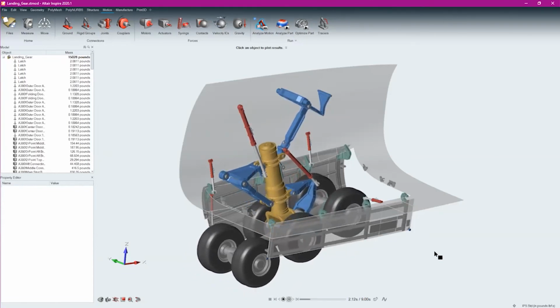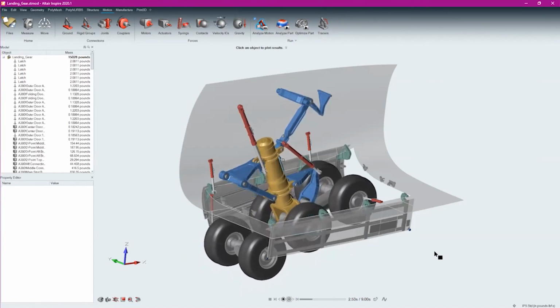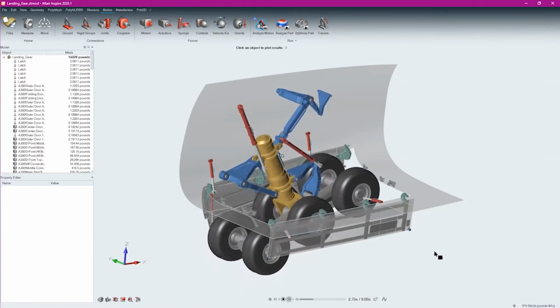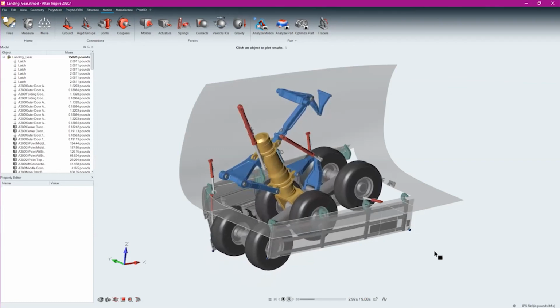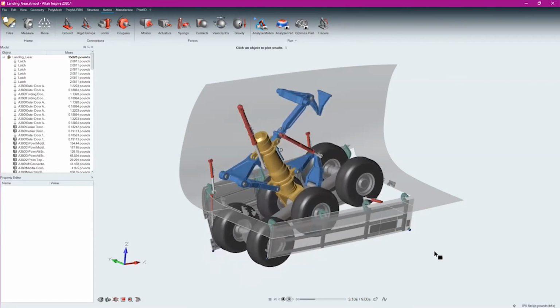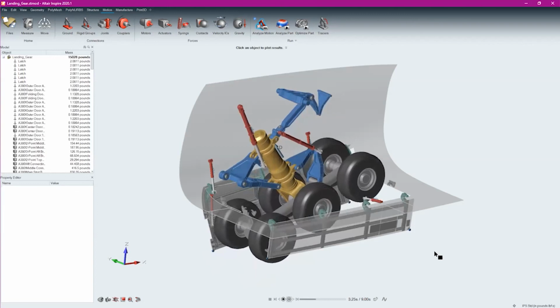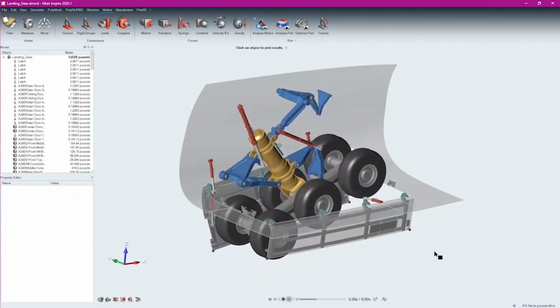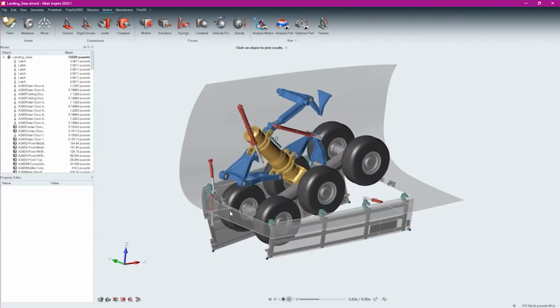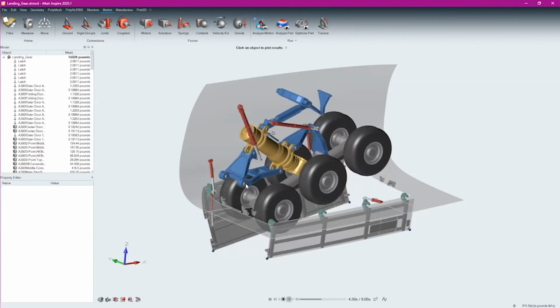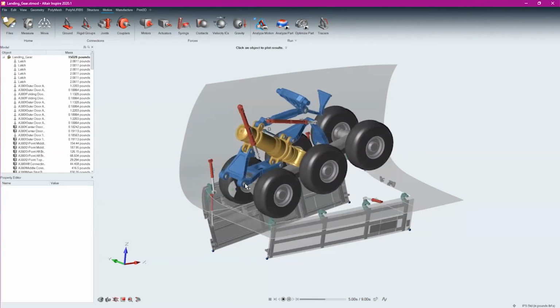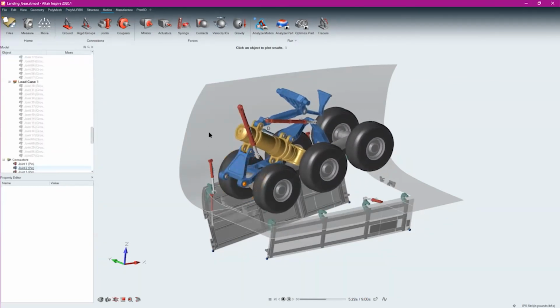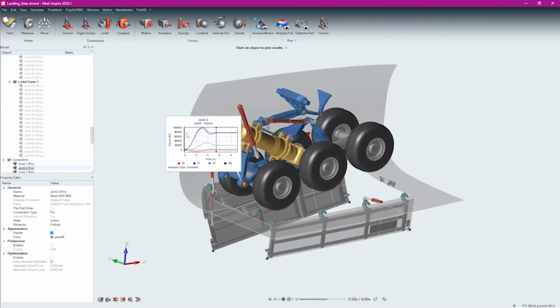All I did with this was, well, whoever set this up, I didn't create this model, was define the joints between the different parts and set the actuators and time them. And now this is the actual behavior of this properly. Additionally, because it's continually calculating things like forces at joints here, the forces can then be used to do structural analysis and optimization.